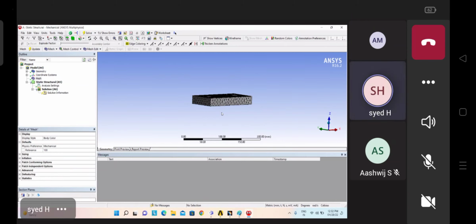Then everybody would go for a fine mesh with more elements, because we get accurate results there. Then why do we use fewer elements? As I already said, time also matters here. Sometimes you don't have that much time to solve. You cannot find a big difference in results, but you can find a little difference here.